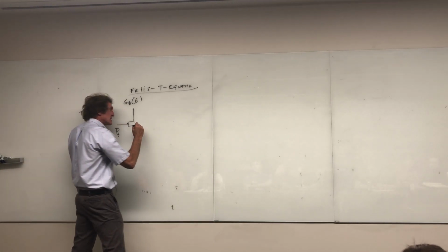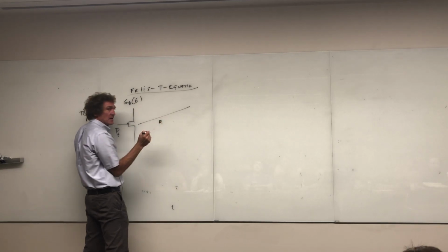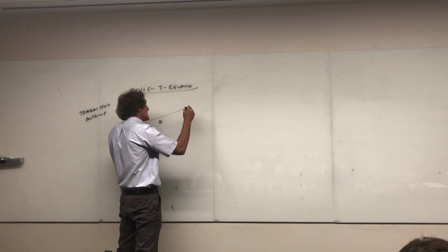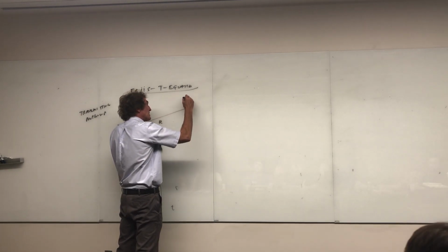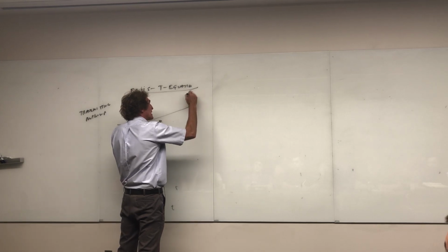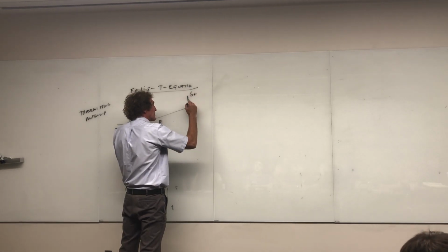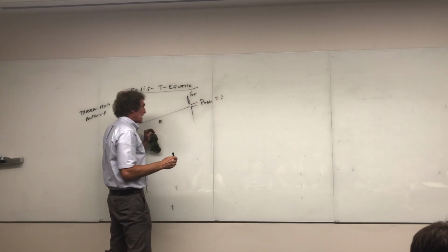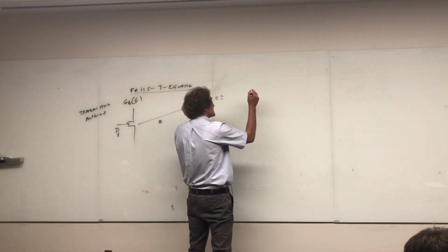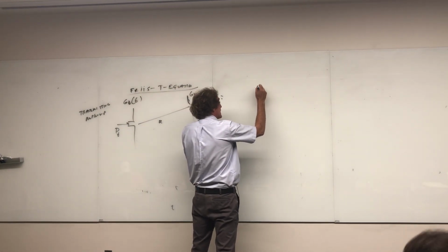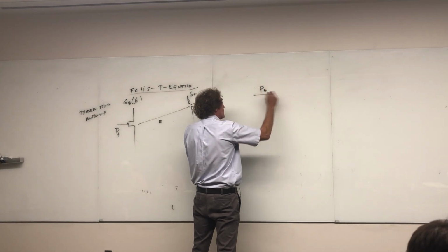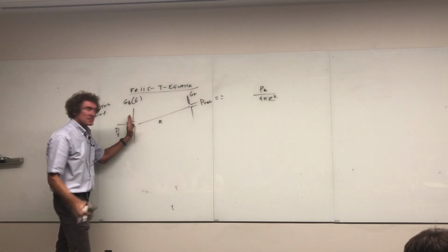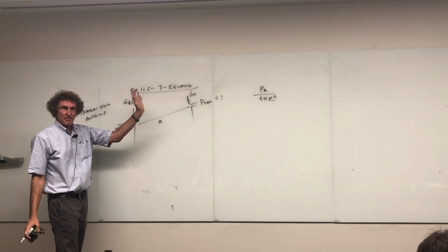It's at a distance r from another antenna. Now, this antenna does not have to be aligned for maximum amount of gain or anything. It could be misaligned, but it's got another antenna up here, and this is going to have the gain of the receiving antenna right here. And now I'm going to find out the power received. That's what I'm after. And if that's so, the way it works is this. When I talk about the actual transmitted power, PT, over 4 pi r squared, that's my starting point. That's what the power density is from this antenna if it's isotropically radiating that power.